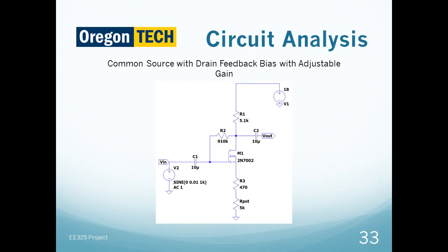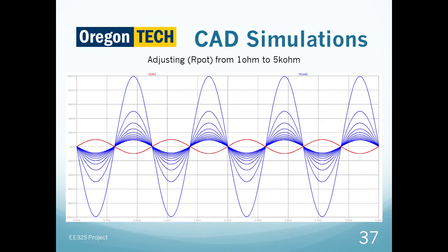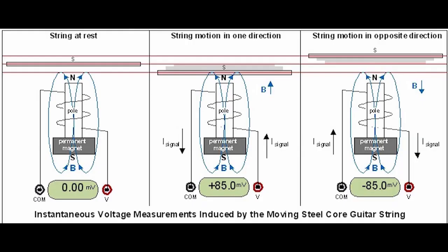The amplification of the signal takes place at the input and output. First, the input signal is amplified by a MOSFET with drain-to-gate biasing and with variable transconductance gain as controlled by a potentiometer at the source. The drain-to-gate feedback biasing ensures that the MOSFET is always saturated. The potentiometer allows a variable gain from just under 1 to 10. This is to ensure the input signal has an appropriate amplitude going into the MFB filter.